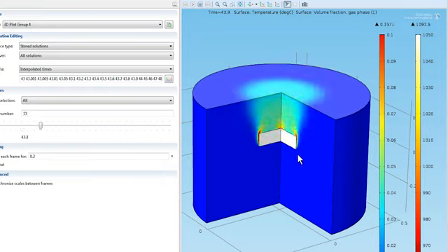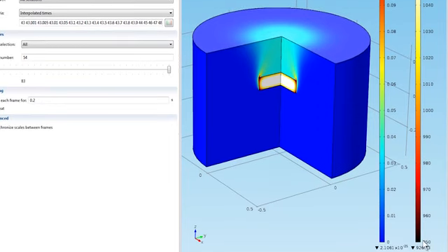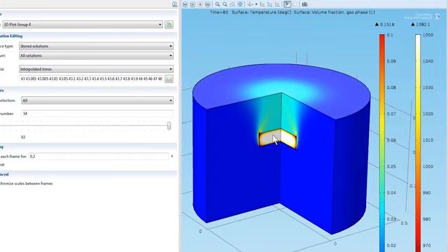This video shows about 40 seconds of the cooling process, during which gas bubbles are quickly formed along the walls of the puck and then float up and out of the top surface. During the 40 seconds, the temperature in the outer areas of the puck drops from over 1050 degrees C to under 950 degrees C, while the interior of the puck is still relatively hot.